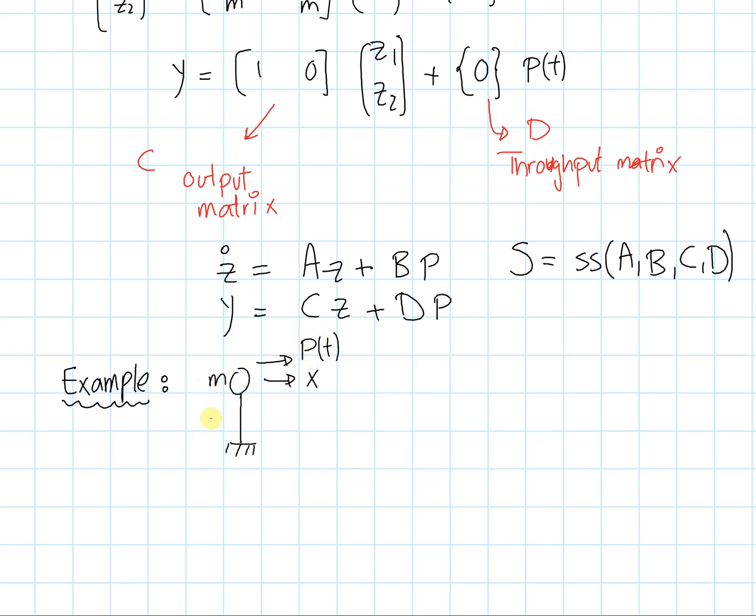We have mass, and we have k and c as the stiffness and damping parameters. And we're told that the mass is equal to 50, some sort of units. That's arbitrary right now. We have stiffness that is equal to 100, and zeta that is equal to 0.1. So if I want to know what my c value is, I can always do 2 m omega_n zeta, with omega_n equaling the square root of k over m.